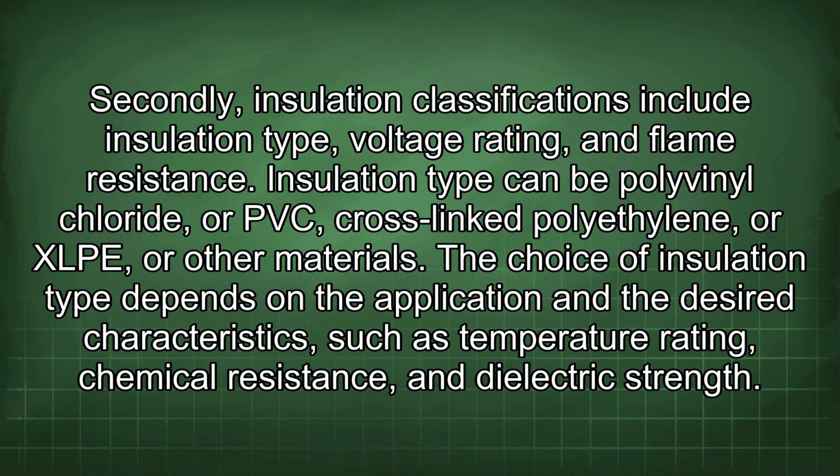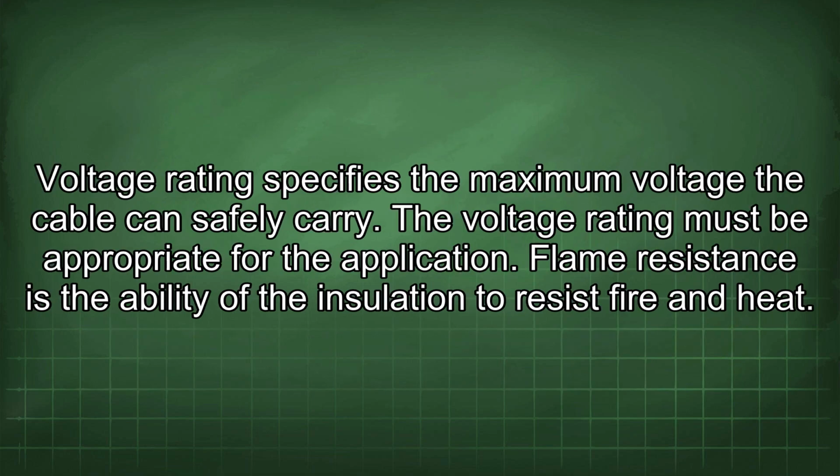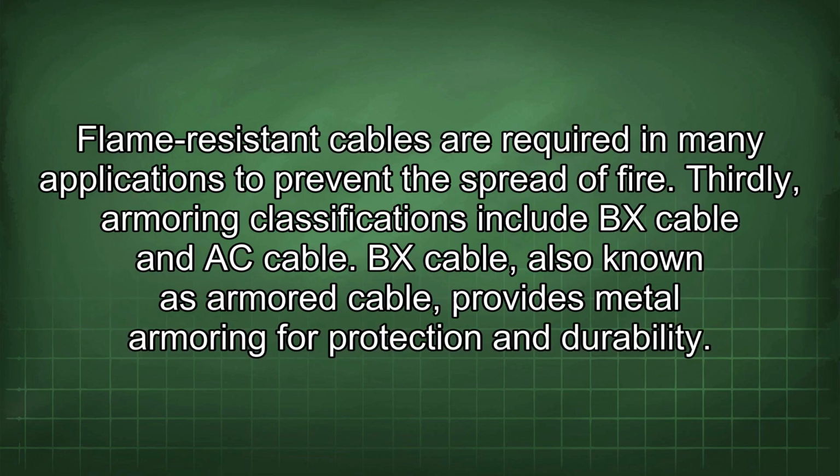The choice of insulation type depends on the application and the desired characteristics, such as temperature rating, chemical resistance, and dielectric strength. Voltage rating specifies the maximum voltage the cable can safely carry. The voltage rating must be appropriate for the application. Flame resistance is the ability of the insulation to resist fire and heat. Flame-resistant cables are required in many applications to prevent the spread of fire.